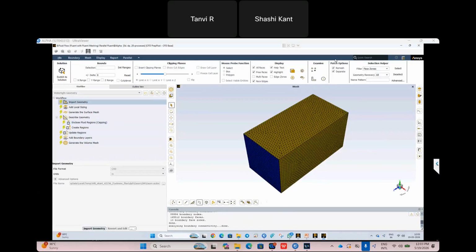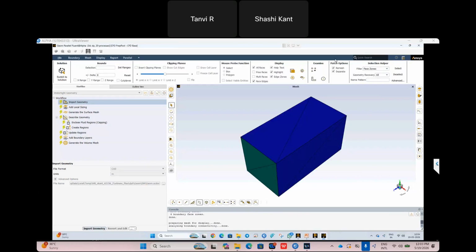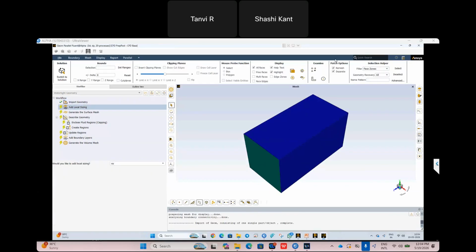You can play with the aerodynamic shape and see the responses. In terms of coupling or integration with the motor impellers, that you can also do. You can import them and define the RPM of the impeller, so you can understand the thrust generated by the impellers, how much it is, and whether the flying mechanism is working properly or not. All of that you can do using the coupling of the complete simulations. Okay.